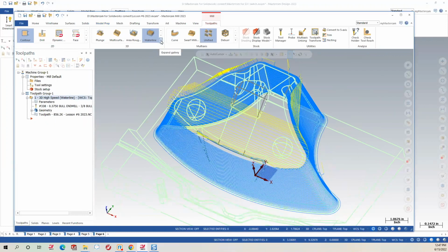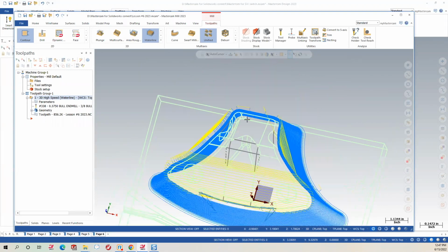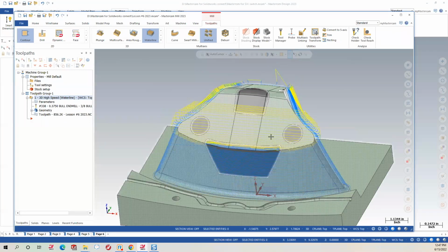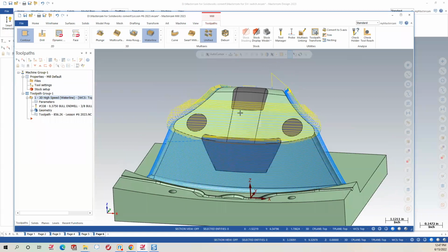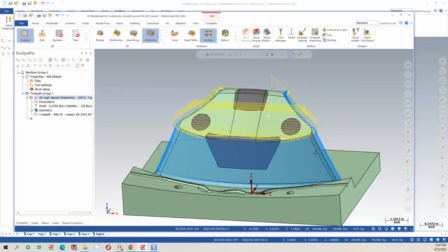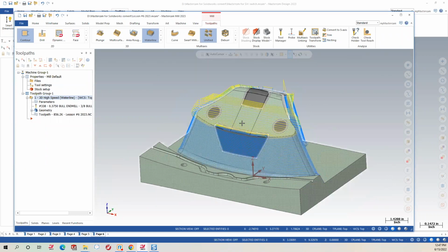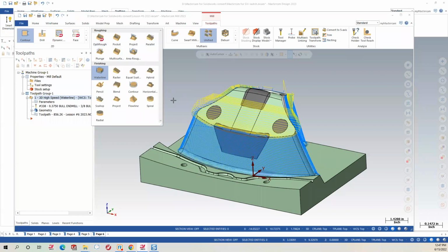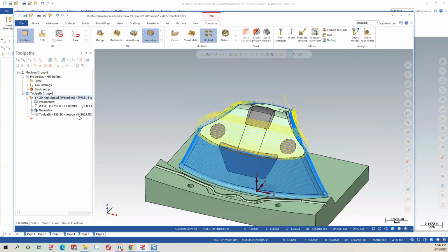With high-speed toolpaths, you're allowed to have multiple containment boundaries, one for the outside of the part, one for the inside of the part. And Mastercam's doing a very good job of, to me, a pretty decent clean toolpath. I've got a little work to do with my rapid moves on and off the part, although that might scare somebody out on the shop floor. But other than that, I've got that all roughed out or finished, and I'm ready to run my OptiRough toolpath and say just OptiRough the whole thing, equal scallop the top, and I'm ready to go.